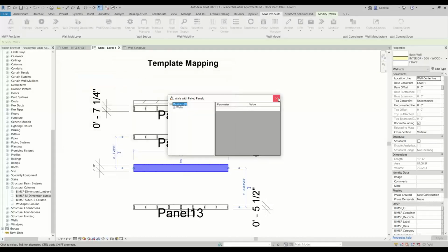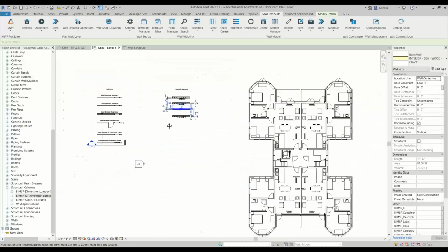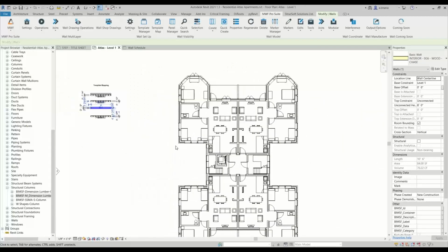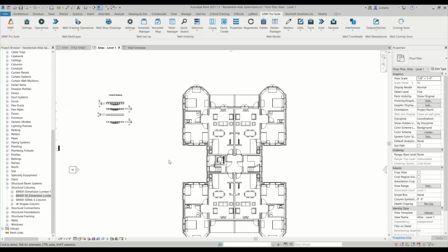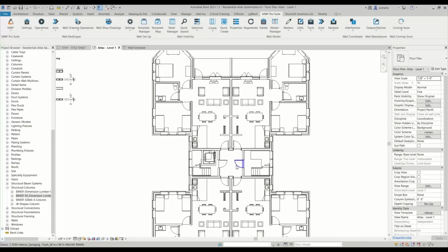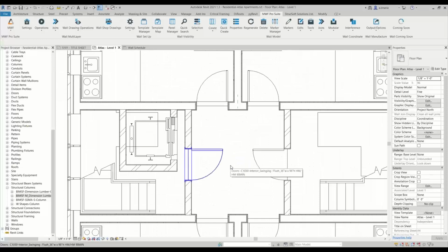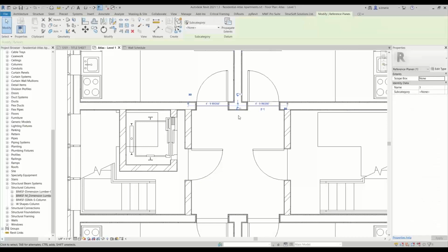All right. So now what we have to do is recreate our chase walls. Instead of recreating our chase walls just for this location, I want the chase walls to use a central location as their guide to align the studs, okay? So the center of my building is here, the middle of the door and the middle of that wall there. You can see we already have a reference plane there.